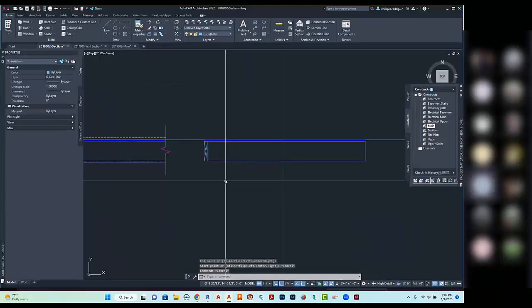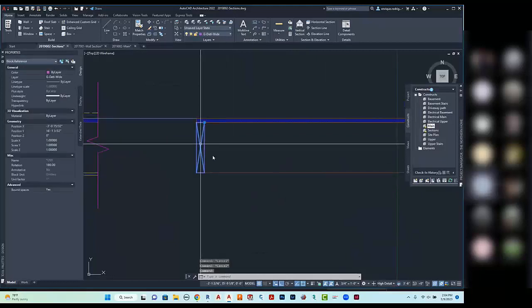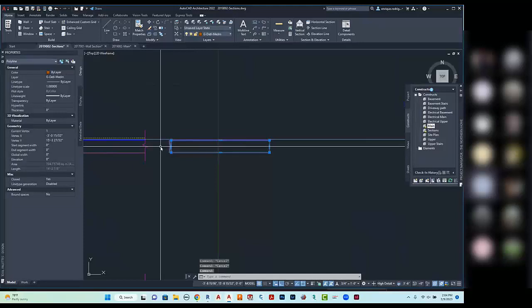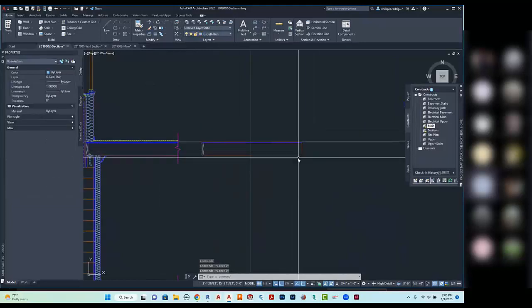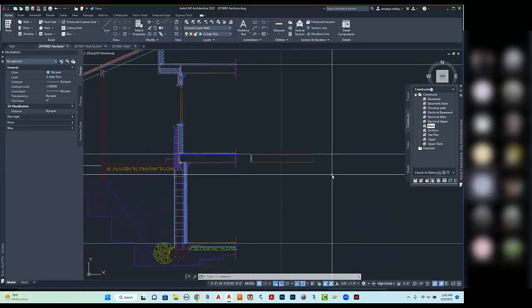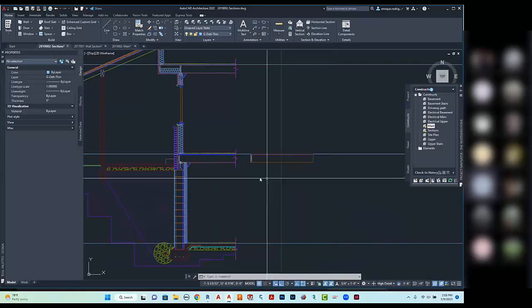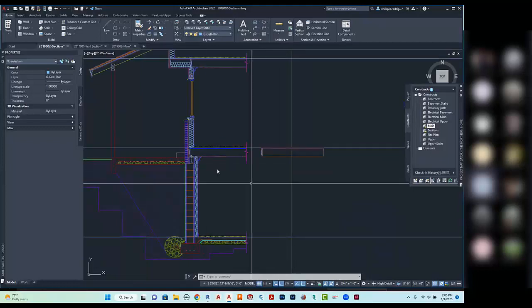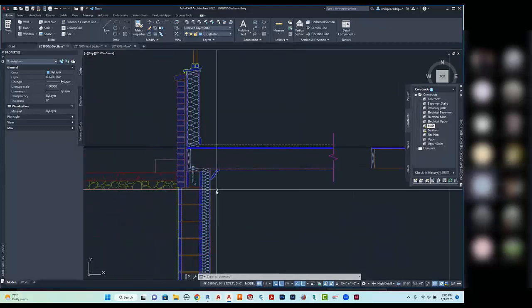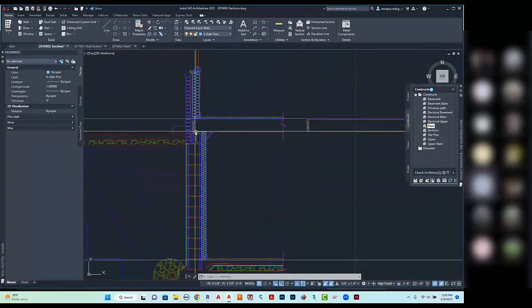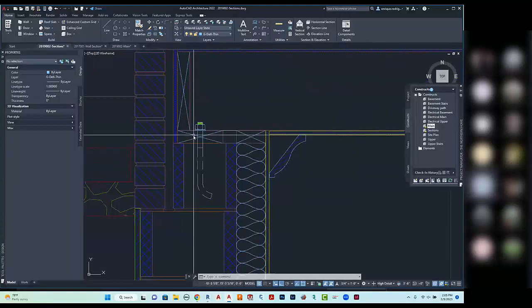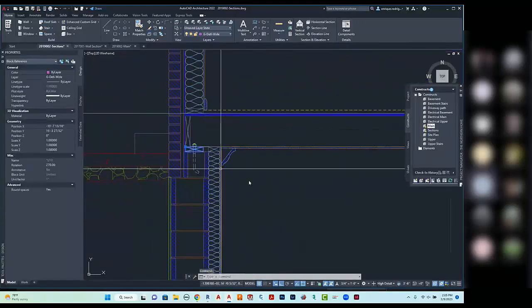So now we have the ribbon joist, which is 2x10, and we have our floor joists. Now, this will add a note to it so it clarifies it, which will let them know that it is at a certain number of inches on center as required by the structural framing for the loads that are coming down on that. All right, let's continue to the sample section. Let's continue working our way down, all the way down to the basement. The next item that we're going to do is what we call a sill plate.